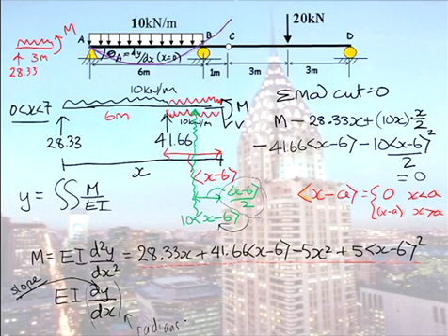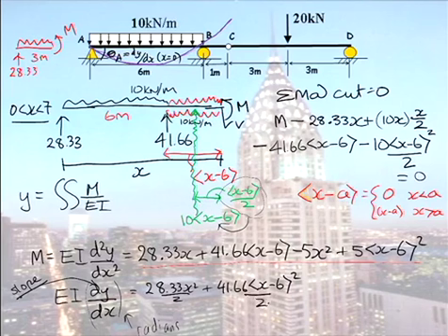So let's continue now. We're going to integrate this once, and this part of it, I know from experience, you can all quite happily do the integration. The thing to remember is we do not expand these singularity brackets out when we integrate them in their bracketed form. If we attempt to expand them out, then we lose the ability to make them disappear.